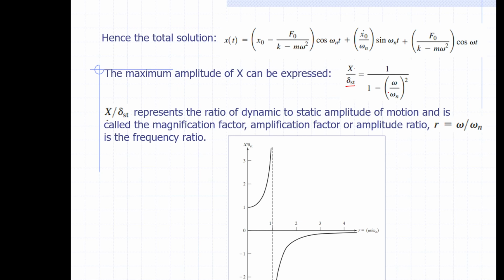You have a vibrating system, and the external force excites the system with a frequency the same as the natural frequency, then the vibration will go higher and higher. I mean, the amplitude of the vibration gets higher and higher.